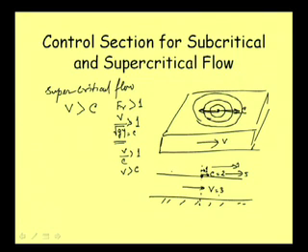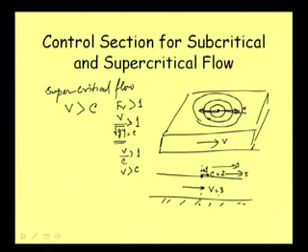In an unsteady flow situation, when we discuss the characteristic equation, we will see that the characteristic curves are always in the positive direction in case of supercritical flow. That part we are not discussing here. I am trying to explain this with a very simple, familiar situation, and that is why the statement we passed in the last class: in case of supercritical flow, any disturbance created at any section will not affect the upstream of the flow.